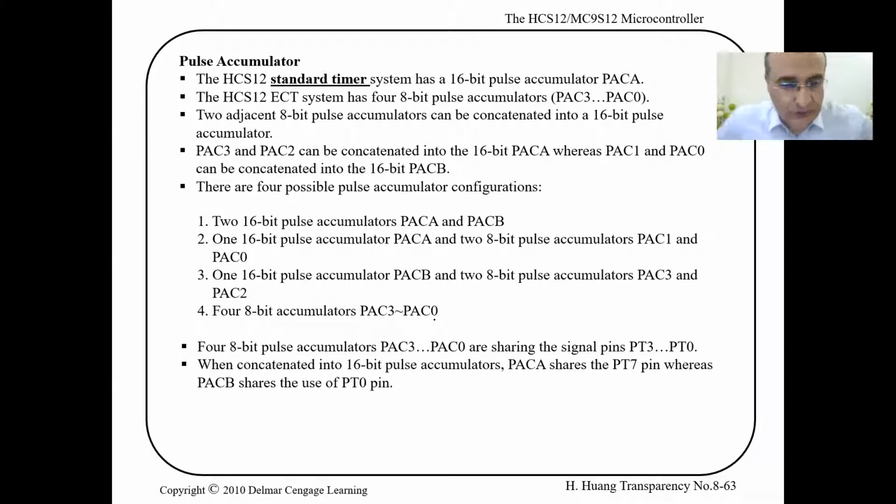Examples. Okay, pulse accumulator. I'm going to go through it real quick. The standard HCS12 timer, well, we have an enhanced timer on our controller. In this enhanced timer, we have pulse accumulators. What is a pulse accumulator? It's like a register that whenever a trigger comes, a pulse, let's say, this counter or pulse accumulator will increment. It's a register that counts up. The pulse will act as if it was its clock. A rising edge came, the accumulator will increment.